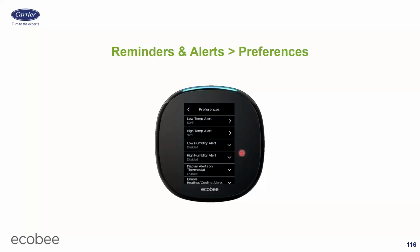That's not safe. It's bad for human comfort. It causes indoor air quality issues. Mold growth could thrive. We got to solve that. What do we do to solve it? Well, we need to take a look at resizing your system, or we need to change the fan speed on your system, or we need to add a dehumidifier, which I would never say that, but someone might. I need to find a solution for you.